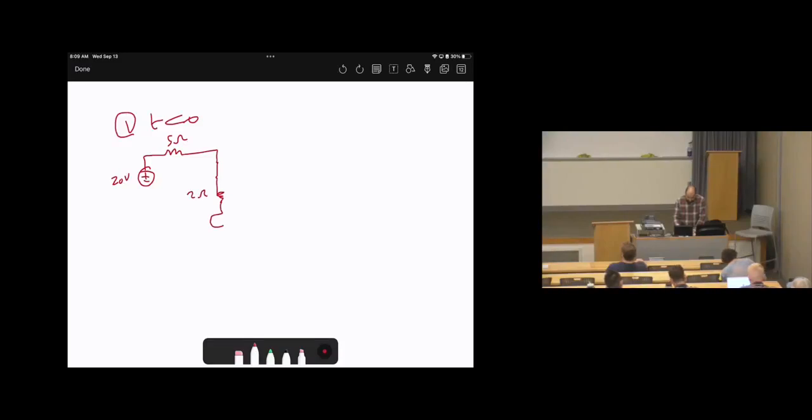Then there is a voltage source of 50 volts. Then we have a resistor here, which is 15 ohms. Then here are the capacitor terminals. The capacitor will be an open circuit. Why? We are at steady state. Our target is to calculate the voltage here, Vc of 0.